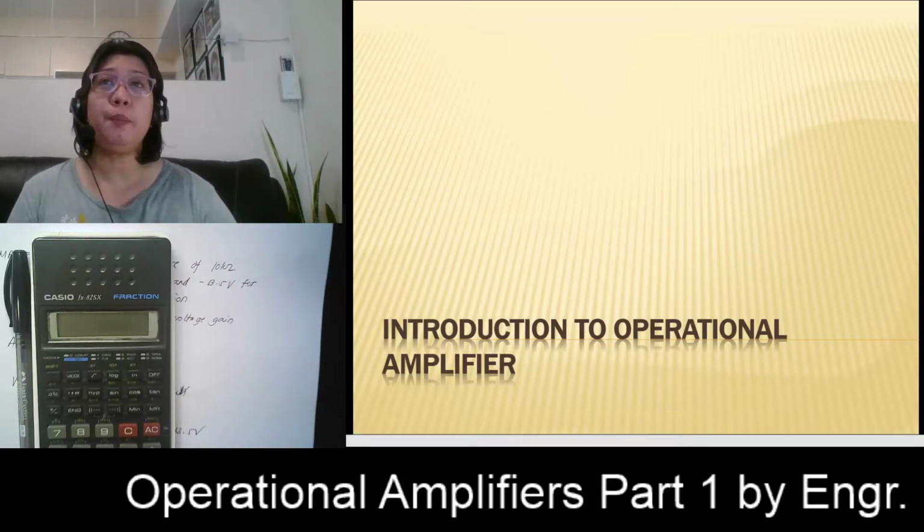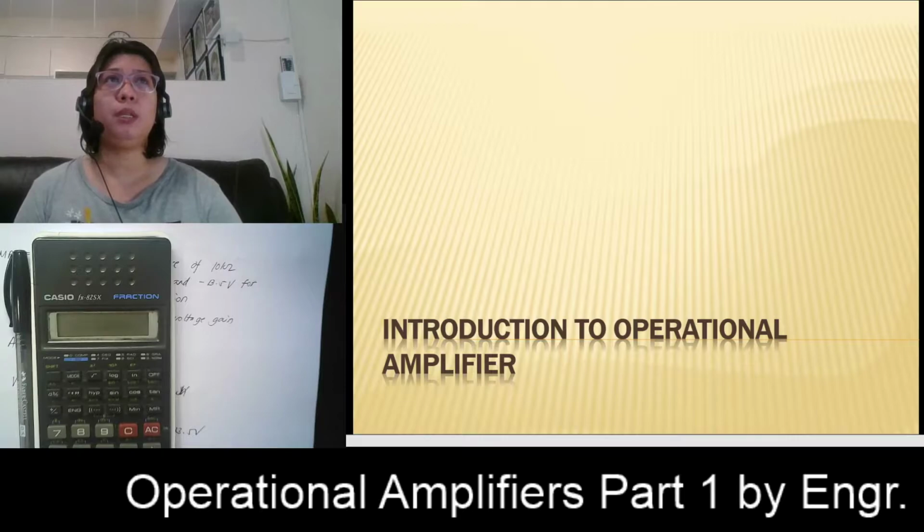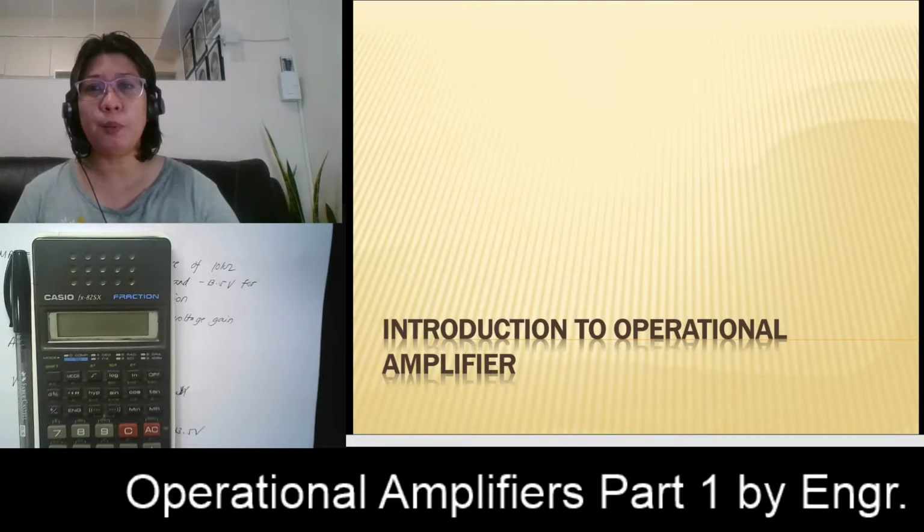Just by connecting two external resistors, we can adjust the voltage gain and bandwidth of an op amp to our exact requirements. And with additional external components, we can build waveform converters, oscillators, filters, and other electronic circuits that we need. That means operational amplifiers are very versatile, in such a way that just by placing external components on them, we can modify their applications.